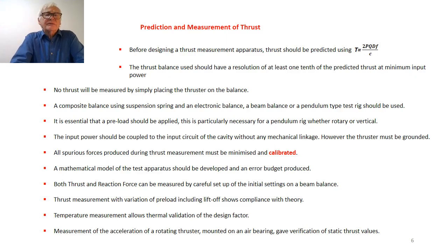Whatever test rig you build, you need to ensure that there is a very small preload applied, and this is particularly necessary when you use a pendulum type test rig, because by definition at the 0 point of a pendulum there will be no preload.